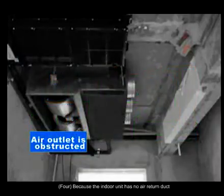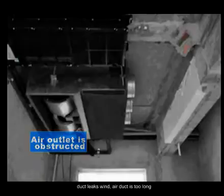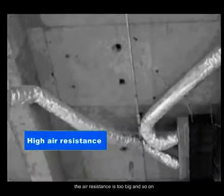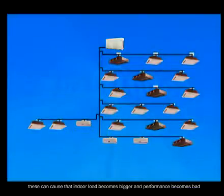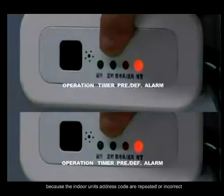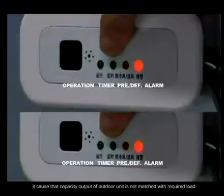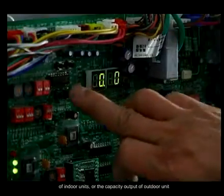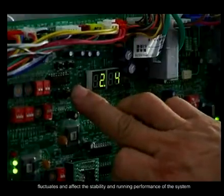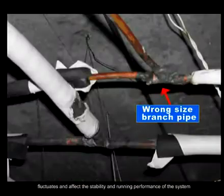4. The indoor unit has no air return duct, the duct leaks wind, the air duct is too long, the air resistance is too big and so on. These can cause the indoor load to become bigger and performance to become bad. 5. The indoor units' address codes are repeated or incorrect. It causes the capacity output of the outdoor unit to not match the required load of the indoor units, or the capacity output of the outdoor unit to fluctuate, affecting the stability and running performance of the system.